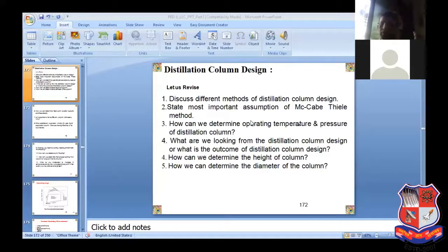All of you must have come across various column operations under different pressures, maybe under CPI, chemical process industries, or some other subjects. When you come across it, a distillation column can be operated, fine, with three options. Pressure inside the column can be equal to 1 atmosphere, or greater than 1 atmosphere, above atmospheric pressure, or below 1 atmosphere.